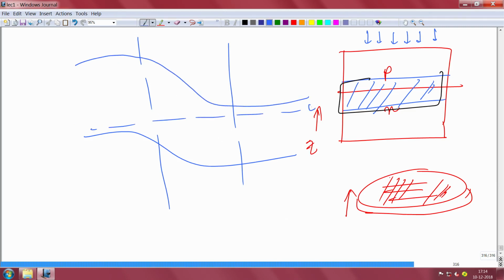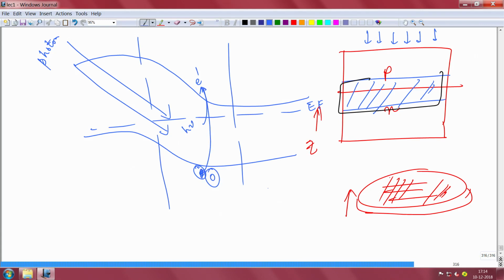So, this is your Fermi level. Any photon that falls in the depletion region is absorbed here. That energy will be used to excite an electron from the valence band. If the energy corresponds to the band gap or more, then an electron will be excited from here to the conduction band. What will remain here is a hole. So an electron hole pair is created for one photon, if it is 100% efficient.